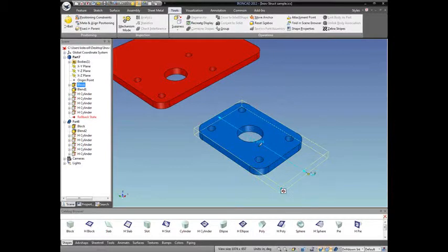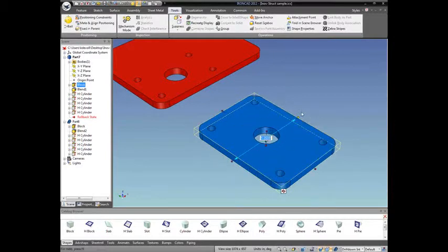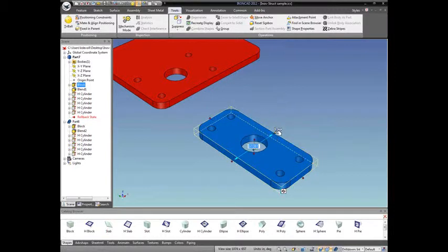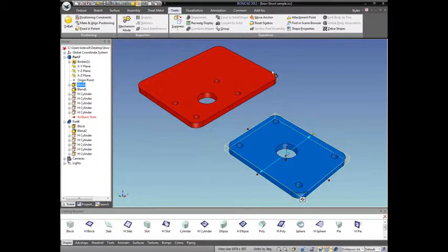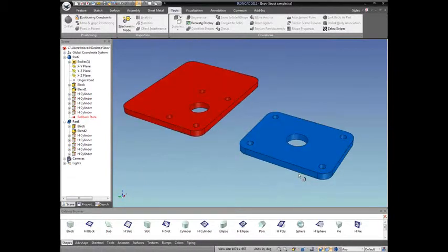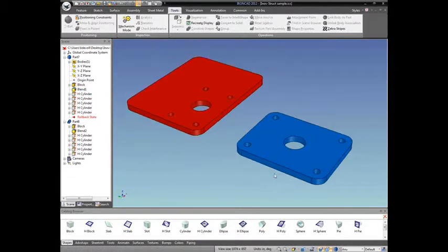So that's the kind of thing where, if a customer knows what the design intent is, then he can capture it quite a bit easier. Now, we could do some similar things in innovative mode with a lot of push-ups. We could put dimensions on here and lock these into place. But the structured mode just makes it a lot easier. So if you toggle over to structured mode, drop a block out, bam, you've started a structured part. You can go on your way. So that's really all there is to that. Fundamentally, that's what it brings to the table.